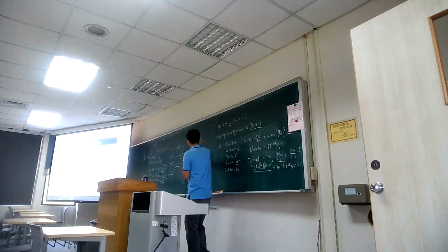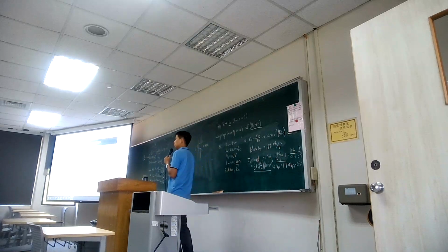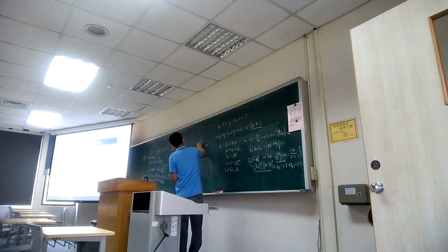So it is a really simplified model. You get an insulator here, so it is a gate function. When we apply gate voltage for NMOS, so here's NMOS, it is conducting with an N channel, electron channel. So when you conduct the electron channel, the voltage should be positive. And once you have positive voltage, you get some negative charge as the channel, and then we get current flow from drain to source.